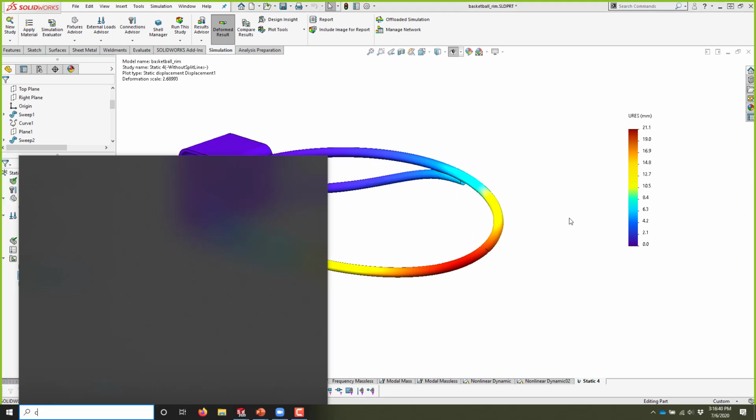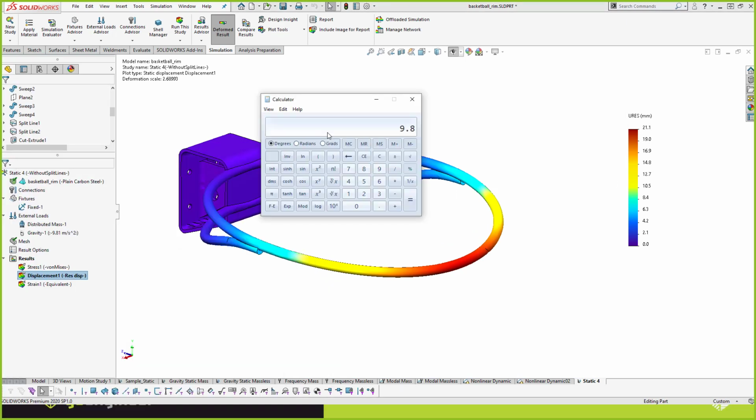Okay, and if I go ahead and punch that in, 9.81 divided by 0.0211, that's the displacement in meters. Take the square root and also divide that by 2 pi, because this is in radians per second. Divided by 2 times 3.14159. According to this rough hand calculation, that's only based on a static analysis, I'm figuring that this thing resonates at about 3.43 hertz.